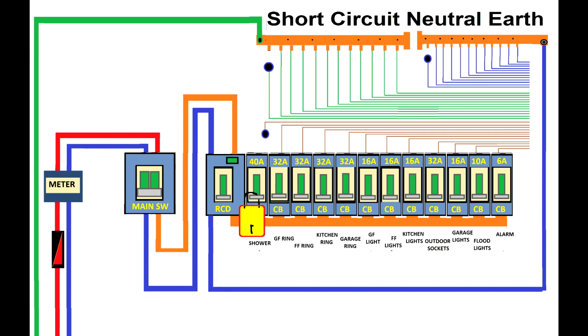Having the faulty circuit breaker secured, you can enable the main switch, allowing the power to reach the RCD. And then you can also enable the RCD, allowing the power to reach the bus bar, which brings power to all the circuit breakers. Now your circuit breaker is safe, no one can activate it. And then you can activate the rest of the circuit breakers, and with the exception of the faulty circuit, all the circuits in the home will have power.